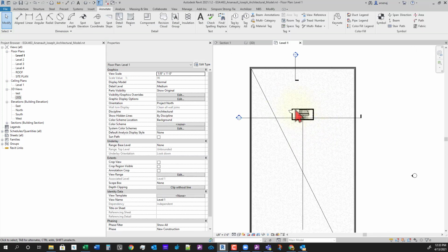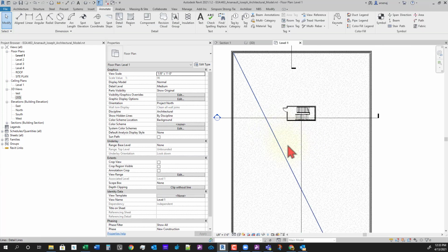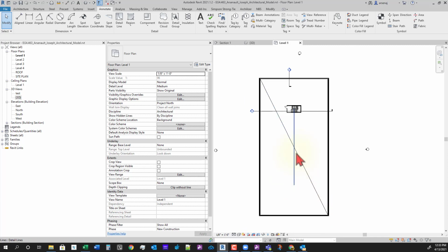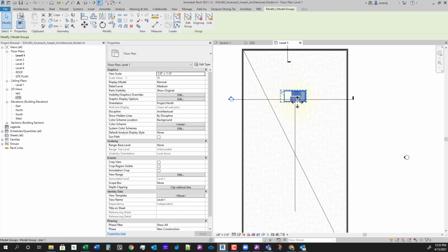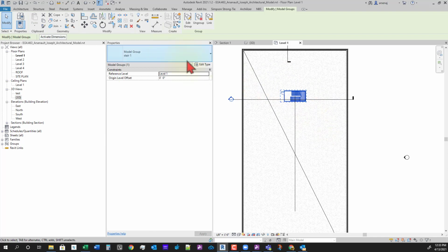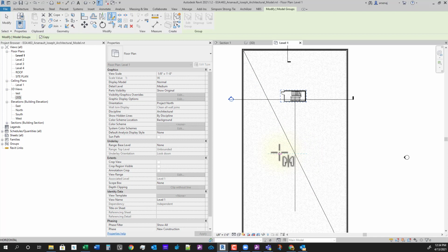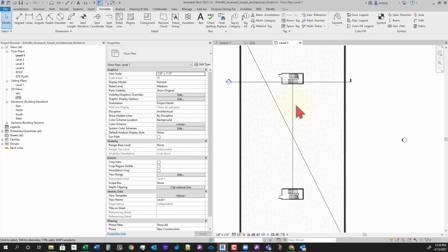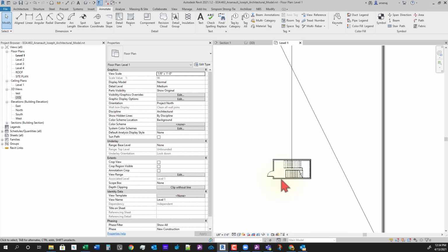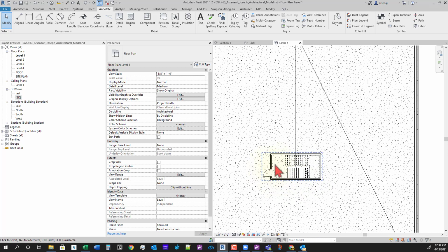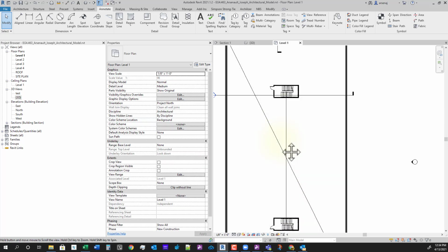And now we have our stair centered on our building and half the diagonal apart from the other stair that we're going to place. So we potentially could now select this stair group and then mirror by drawing an axis and selecting the mid of the line that we drew, and it should pop this stair over here. So now we've got 2 stairs. And again, we would need to cut the slab on the other levels for this stair.